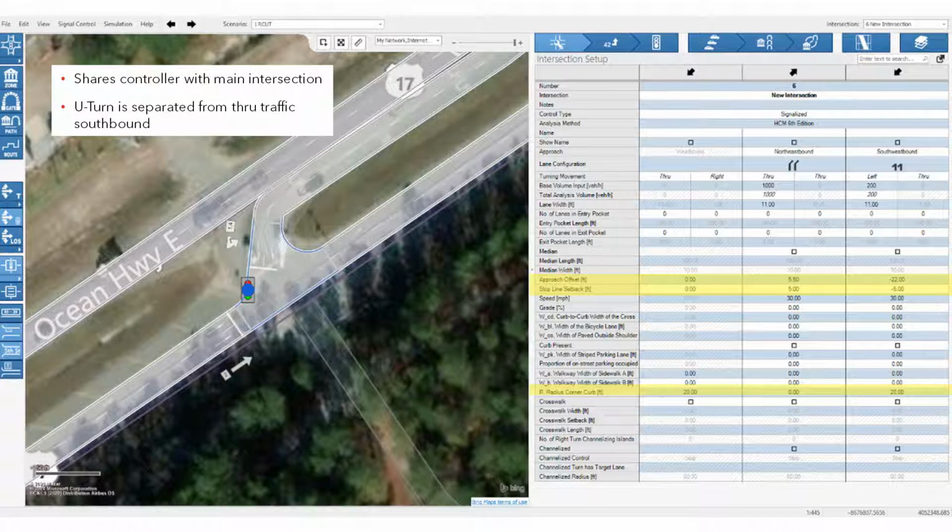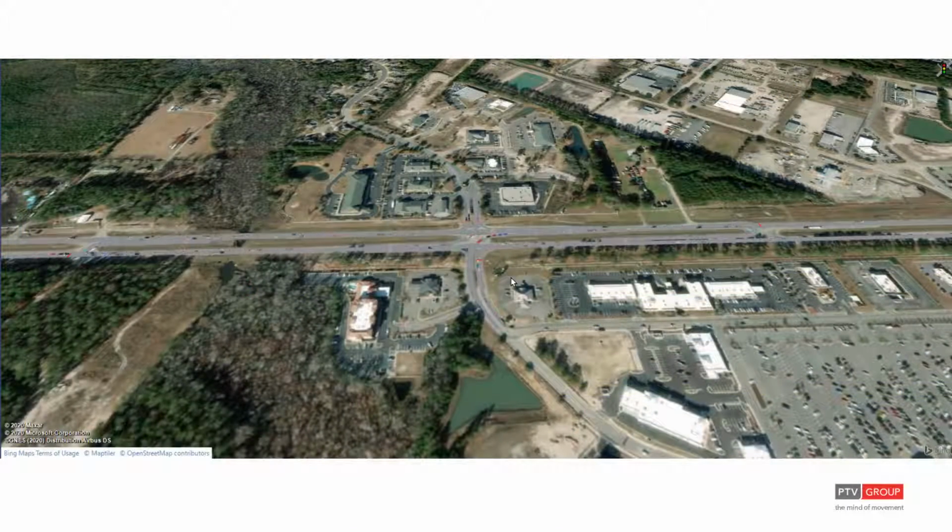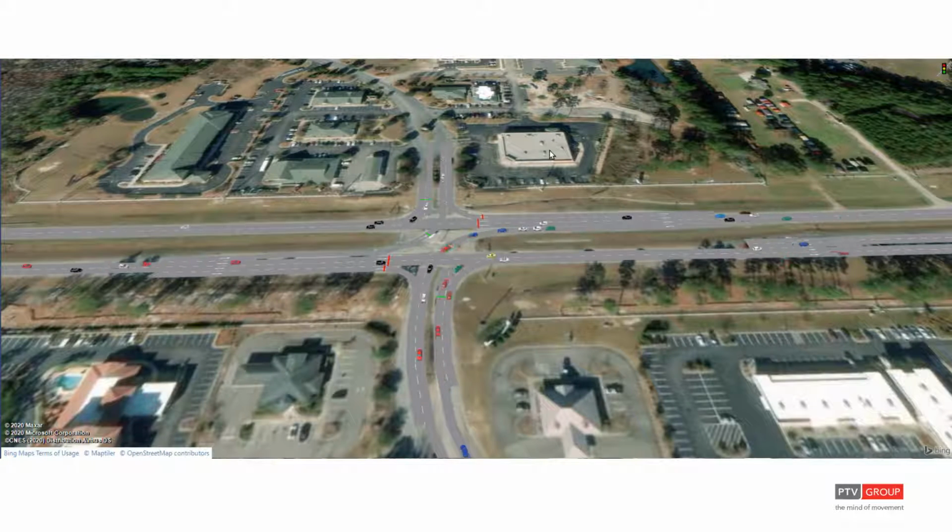And then when you go down to the U-turn intersection, it's using the same features to create that, and you're able to pull off the U-turn in its own separate turn bay and create the same bypass, like you did in the green T for the top through movement there. And that way, that intersection is able to operate like it's supposed to operate. And again, I'm going to show a video. Again, we're matching the background straight out of Vistro, and it's providing a pretty high quality simulation and showing the vehicles where they're supposed to be.